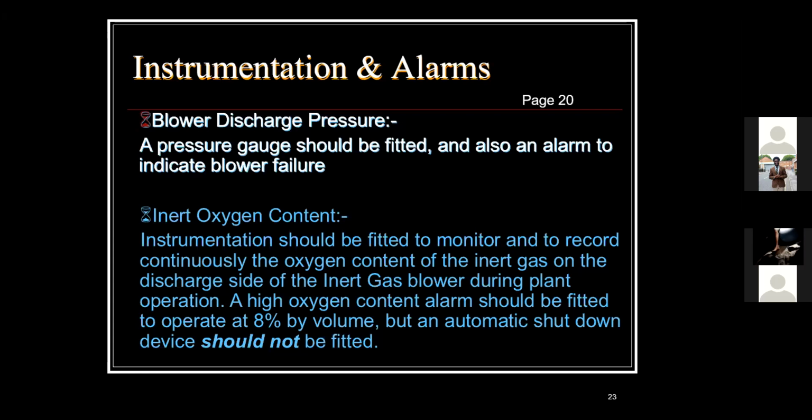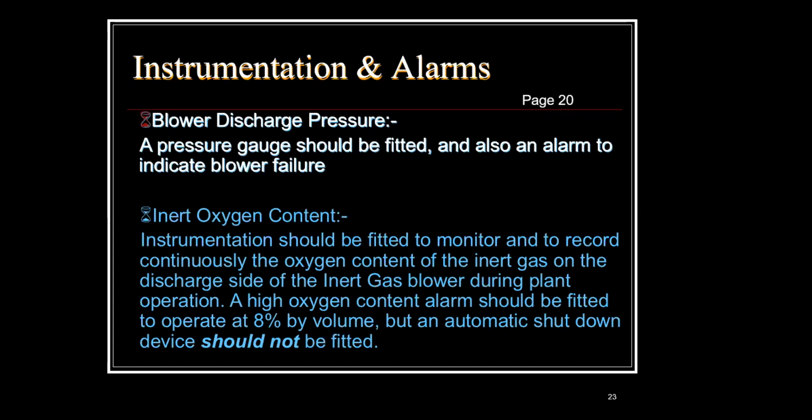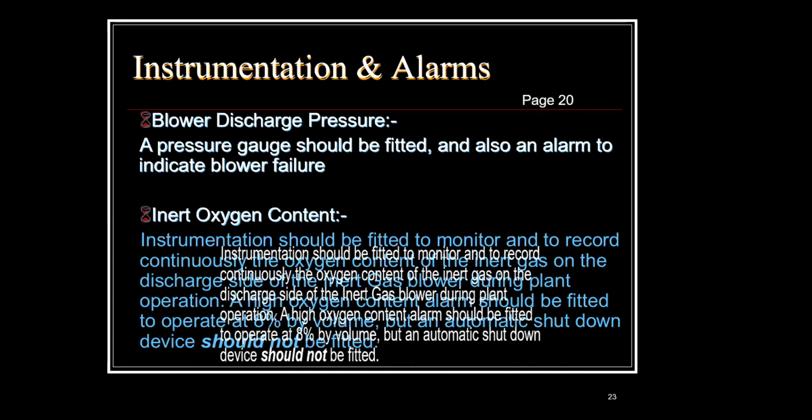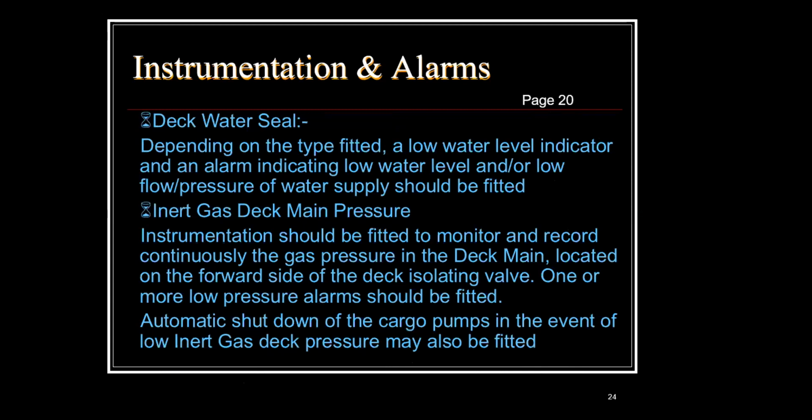And also these instruments, or the analyzers, you have to calibrate at regular intervals to ensure that they are working properly. It's very, very important. You have to calibrate as per manufacturer instruction. Sometimes you just have to carry out a quick bump or span test to ensure that it's working well. So it's very, very important for us to know about the settings and the calibration.